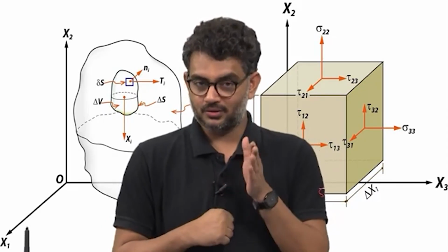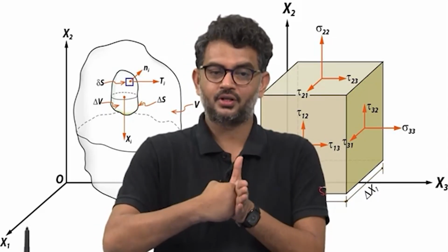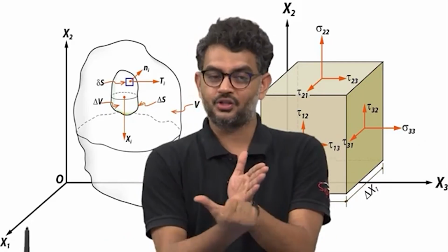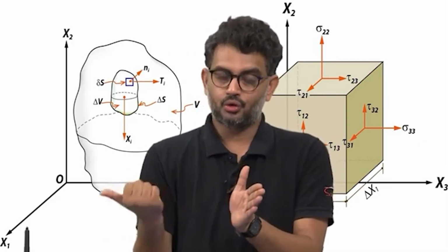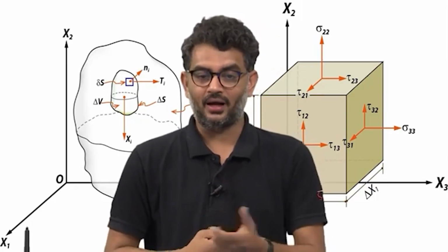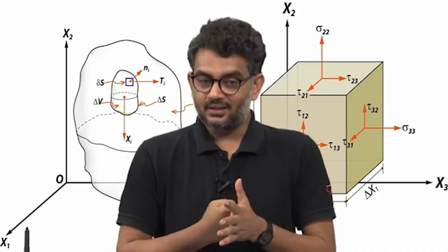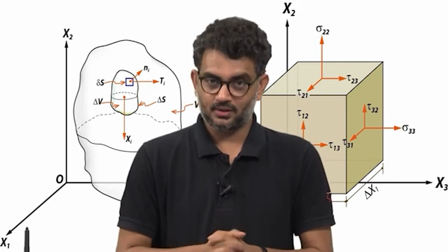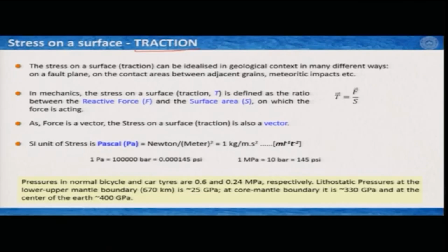that is not stress. Stress is: I am applying this force and my left palm is pushing with an opposite and negative force to the force being applied by my right hand, and this force is the reactive force. It acts following Newton's third law, and this force divided by the surface area is the stress generally defined. So, the stress on a surface, or you can say traction, we will define as T, the ratio between the reactive force F and the surface area S on which the force is acting.